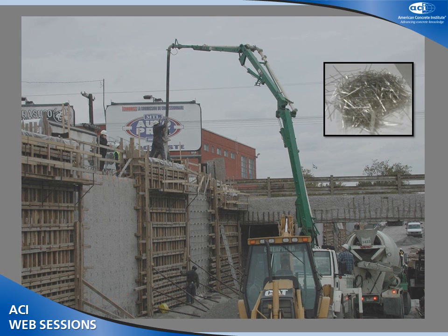And this was the first time that fibers were incorporated in the repair mix. These are synthetic fibers added at a very low dosage of 0.25% by volume. The reason for that is to reduce the crack widths, so they can reduce the need for repair in the future and the need to put on surface sealers more often.